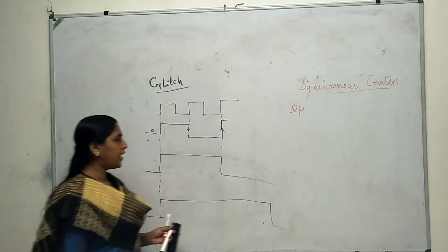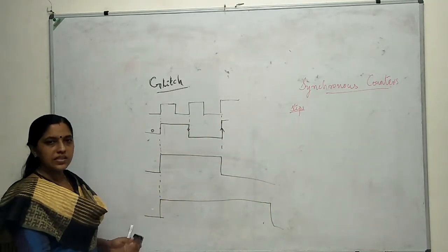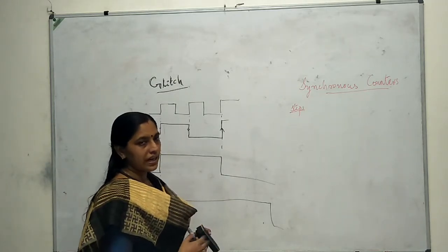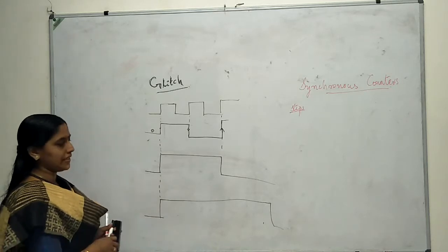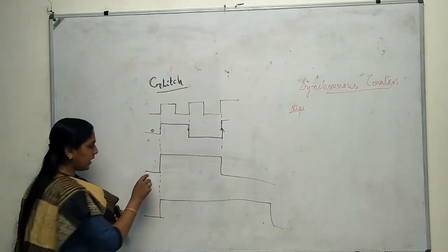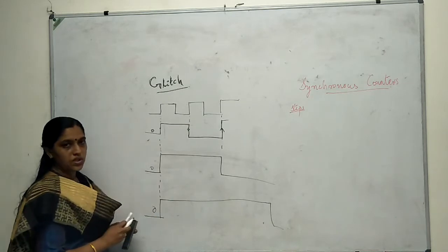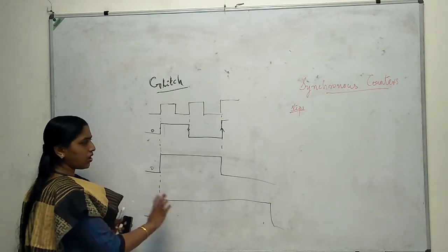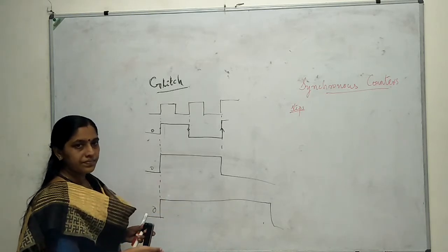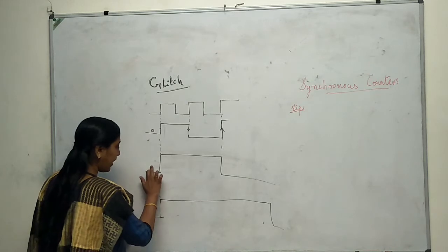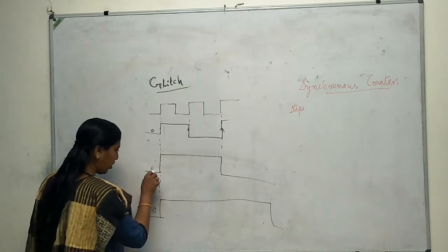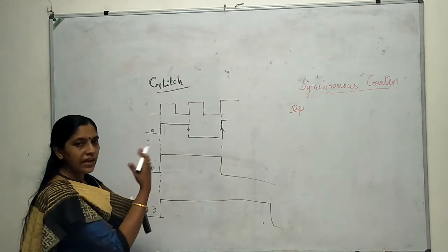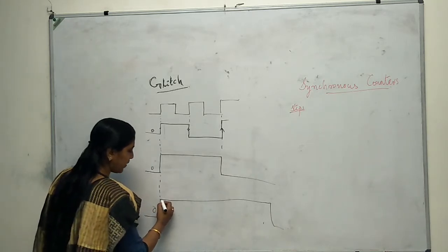Let us assume that we are in this particular situation, and this is a scenario that I am considering. It can happen in any asynchronous counter at any state. So assume that initially I am in state 000. Assume that I am having a down counter, then after 0, I have to start again from 7, right? So I have to start from 7.